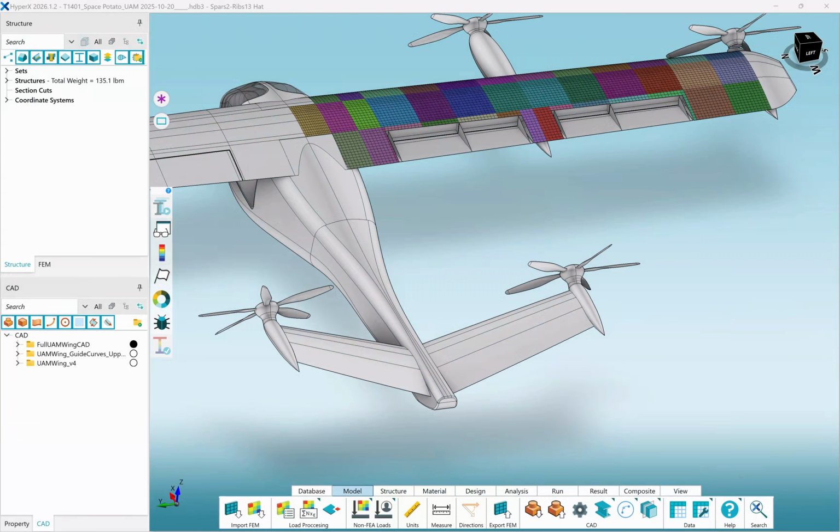For a structure's computed design loads, coming from FEA, HyperX performs sizing by ensuring that the allowable load, based on prescribed failure criteria, is greater for each zone by finding the lightest weight design that attains positive margins of safety. Hyperloads is a visual tool for you to verify and fully inspect results from all three parts of the equation in 3D space.